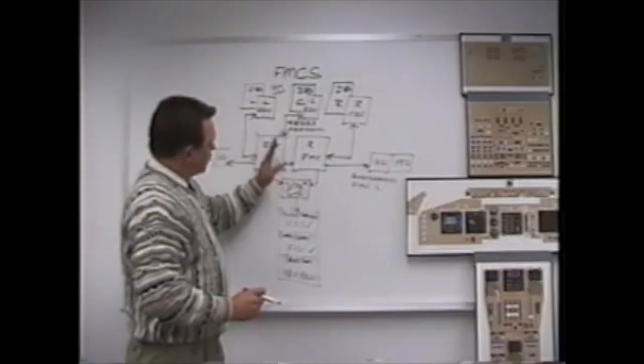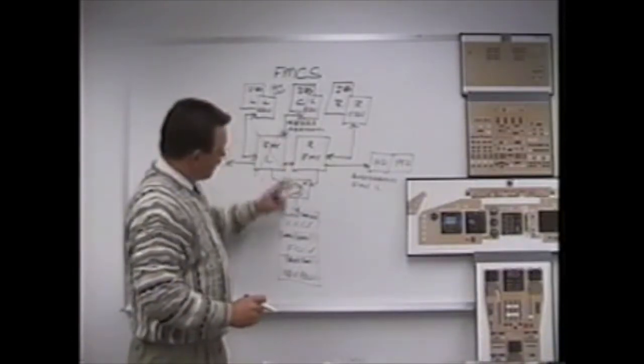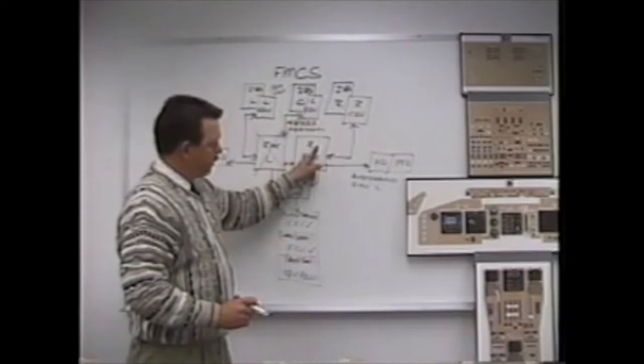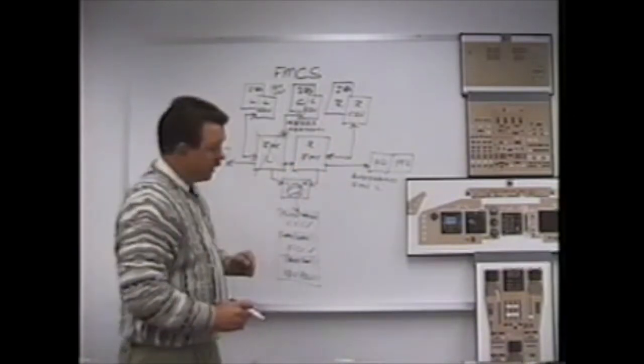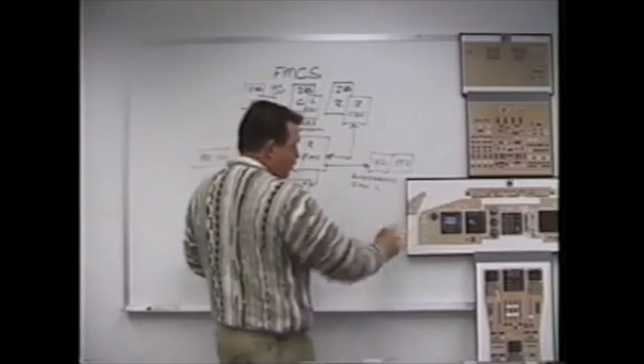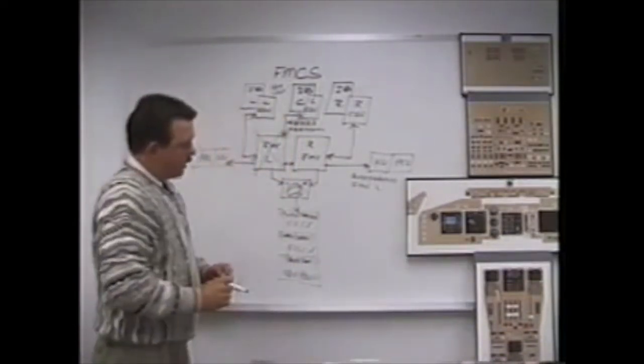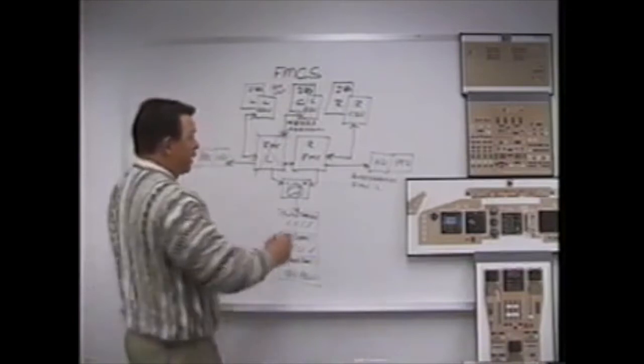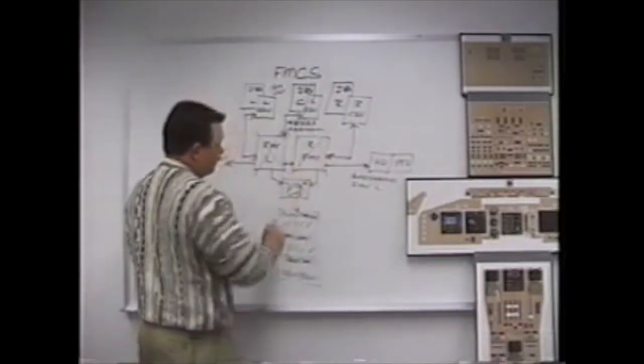Please note that if this FMC was to fail, it will not automatically switch your systems over. The irregular procedure has us doing it. Likewise, this will not automatically switch over. The irregular procedure has us moving that display switch. So then you're having a really bad day, and the right FMC fails too.